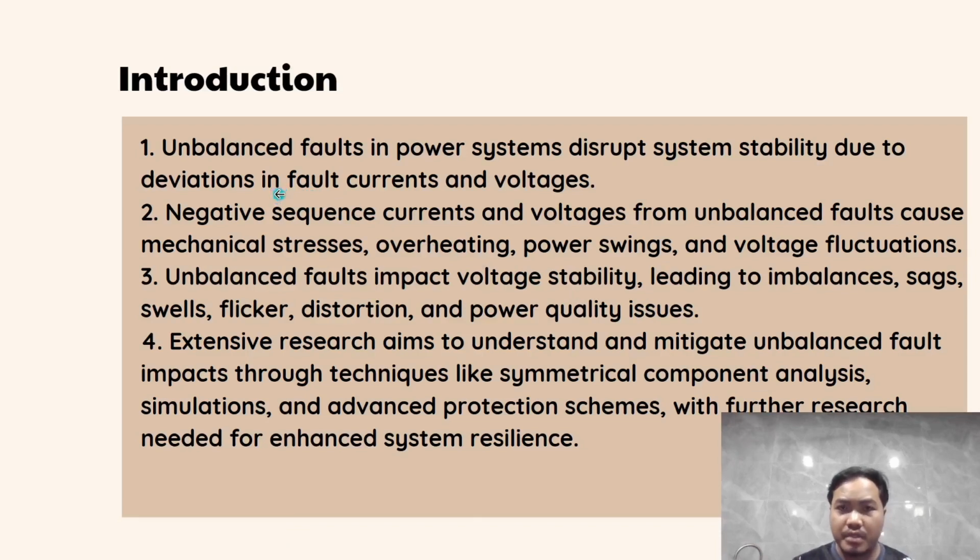Today, I will present about the introduction of our project. First, unbalanced fault in power system disrupts system stability due to deviation in fault currents and voltages. Second, negative sequence current and voltages from unbalanced fault cause mechanical stresses, overheating, power swings, and voltage fluctuation. Third, unbalanced fault impacts voltage stability, leading to imbalance, sag, swell, flicker, distortion, and power quality issues.